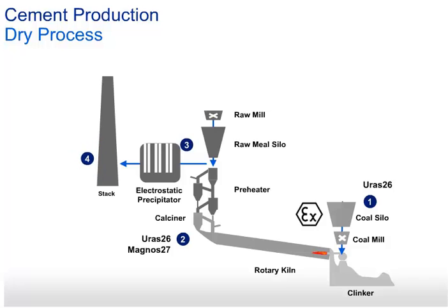Measuring point 4. Stack continuous emissions monitoring. Depending on international requirements for emissions monitoring, a number of gas components have to be measured continuously. The components are CO, NOx, SO2, and depending on the fuel used, additionally HCl, HF, and total organic carbon.